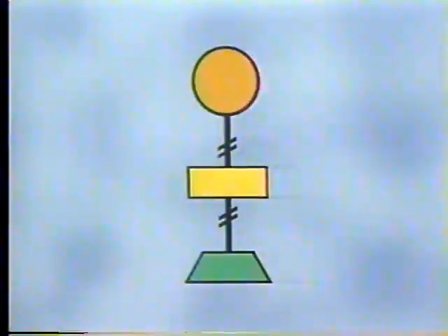To achieve control, a control system performs certain basic functions. It measures a process variable and compares the measured value to set point. If these two values are not equal, the control system responds to bring the measured value back to set point by manipulating a process variable. These functions can be illustrated on a simplified logic diagram. A circle represents an instrument that performs either a measuring or readout function. This one performs a measuring function.